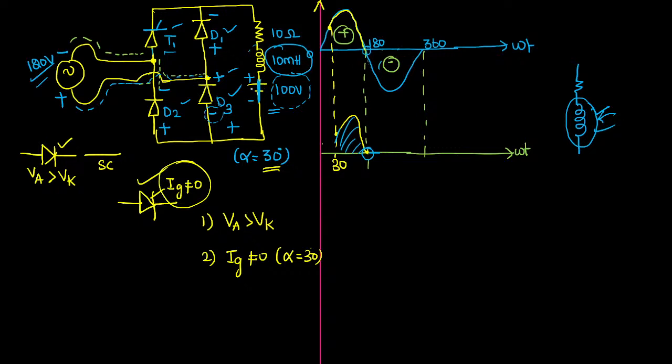Sir, then what will happen? If you observe carefully, under that situation your circuit will once again continue its conduction for a particular time period, and you can observe this. The waveform will continue only for a particular time period, and you can assume till about 30 degree after 180 degree. After that, what will happen? Once the energy becomes less than the value of the supply voltage, then the new polarity will appear. Then diodes D1 and D2 will turn on. Again, you can observe the second cycle positive polarity.